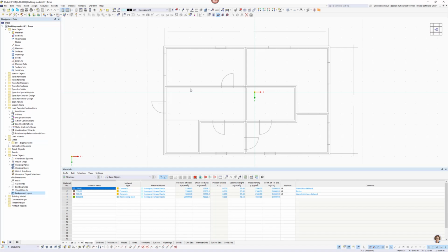Now, when you look for it, on the left side of this building, I will define my stiffening walls, my stiffening elements. So it goes from the left top corner to the middle corner and the bottom middle and the left bottom side. That's where my stiffening core of the structure will be. And on the right side, I will create the facade elements.